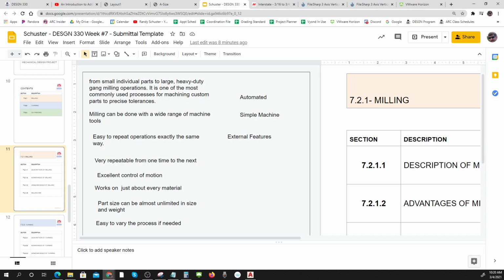So now look, here's the big thing. It only does external. Yeah, you can do glass. Of course, you need to have really good support because you can't vibrate, and you have to have an excellent cutter. You can imagine it's like diamond dust cutters where the little diamond bits go. So glass is really cool.